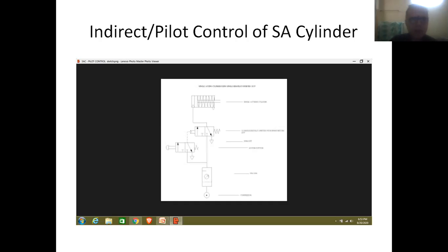It consists of one inlet port that is fitted to the pipeline coming from the compressor, and the outlet of the DC valve is fitted to the pipeline which is entering the port of the cylinder, and finally the exhaust port is fitted to the pipeline that is entering the atmosphere. So friends, just like the DC valve, the pilot valve is also provided with 3 ports. So therefore, it is referred to as a 3-way valve.